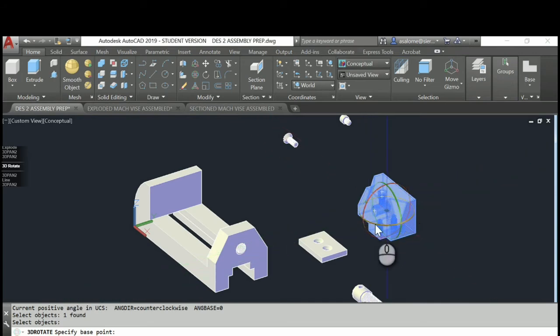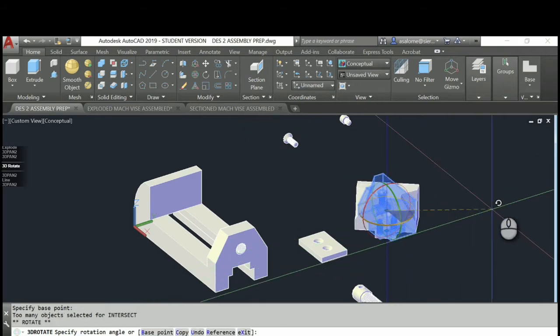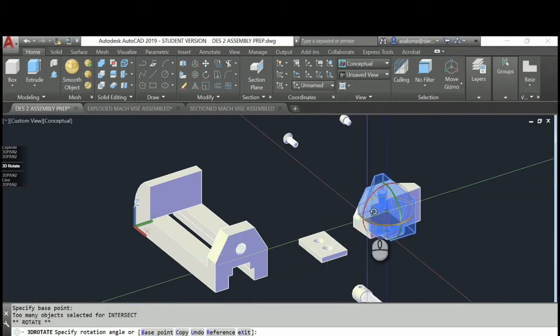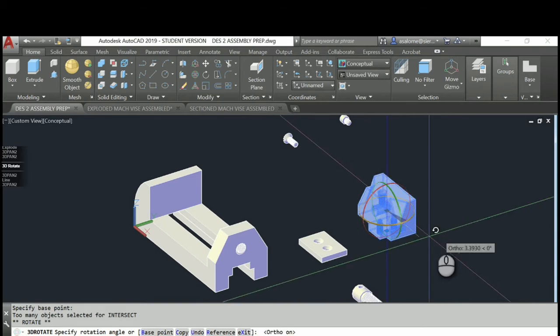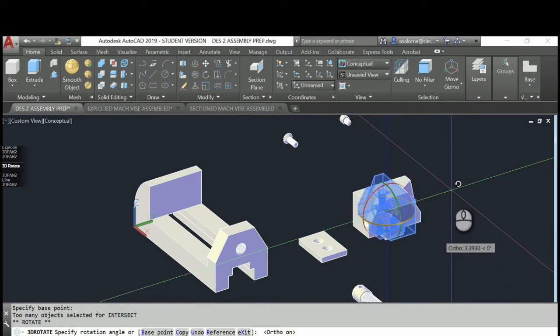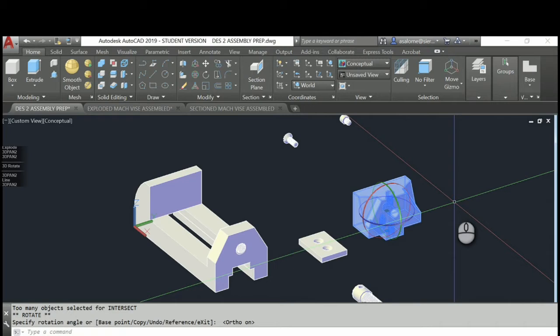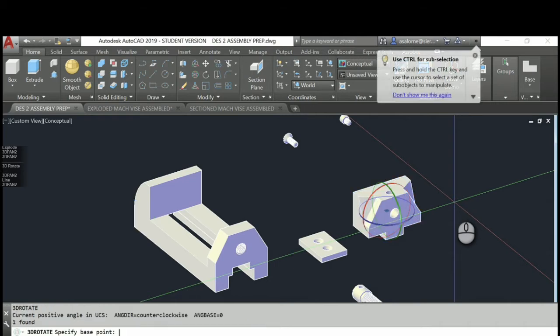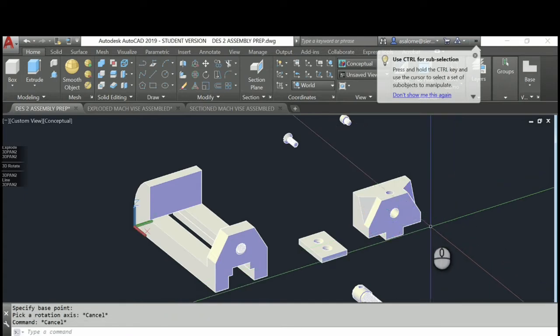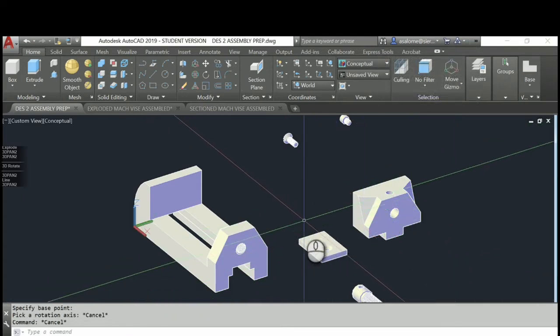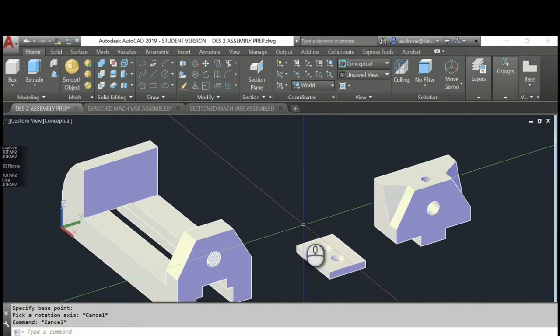We're going to choose the ring we want to swivel it around, in this case blue, and you can pull this. If your ortho is on, you can see which way it's going to go. You can also type in 90, negative 90, depending on which way you want it to go. So we want it going that way. We're done with the gizmo command, so we escape. Okay, we'll see it again. We're going to gizmo a lot.